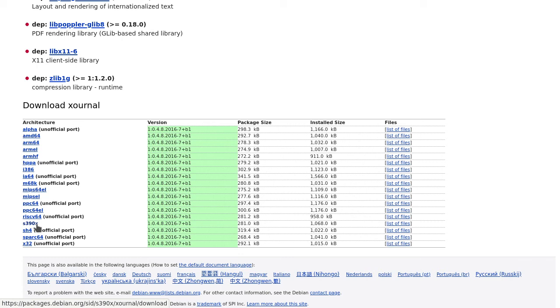So now we are not thinking about how fast is one chip. We are looking at, to get a certain amount of processing done, how much energy is needed. As it turns out, CISC is the wrong answer here. Why? Because a CISC processor has a lot of transistors, a lot of stuff, but at any particular time, not a whole lot of them are actually being utilized, while everything is consuming power at the same time. So the energy efficiency of a CISC processor is actually quite poor.